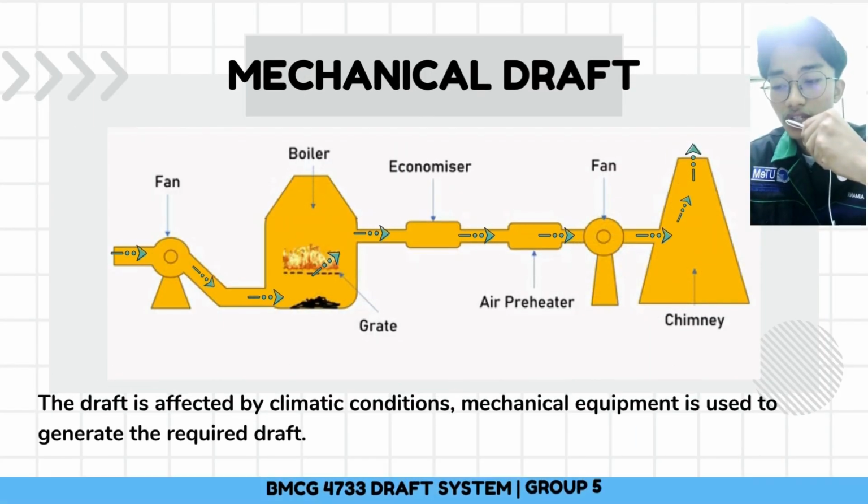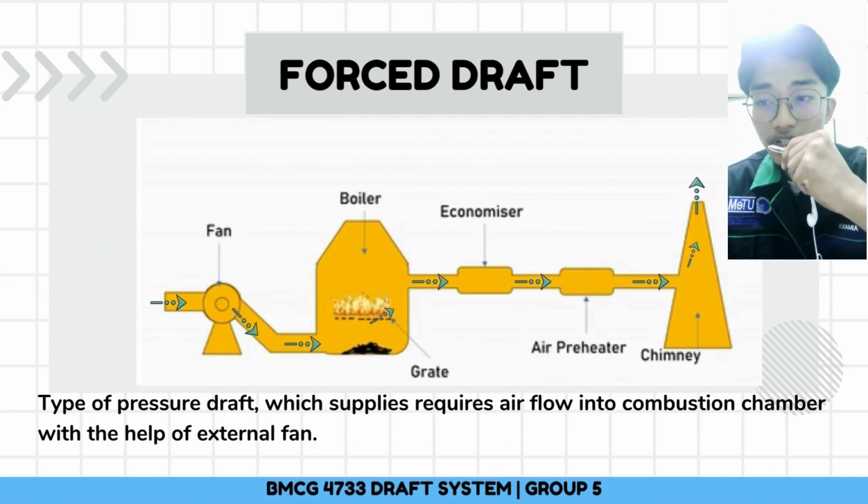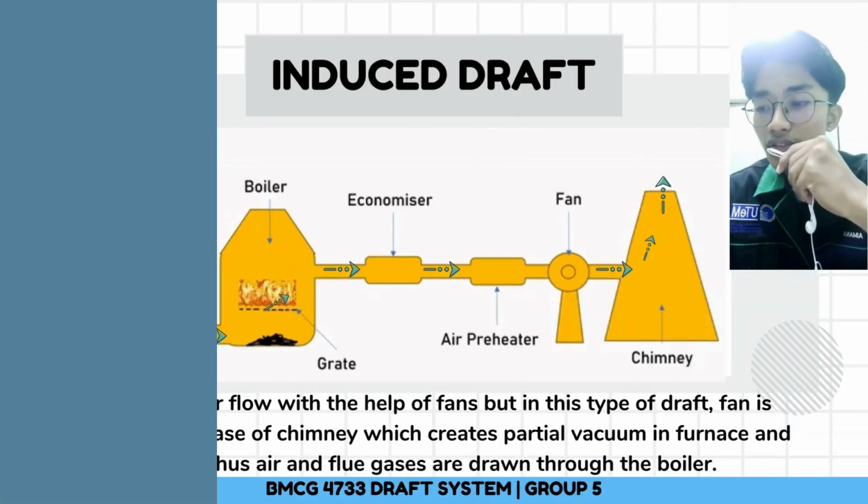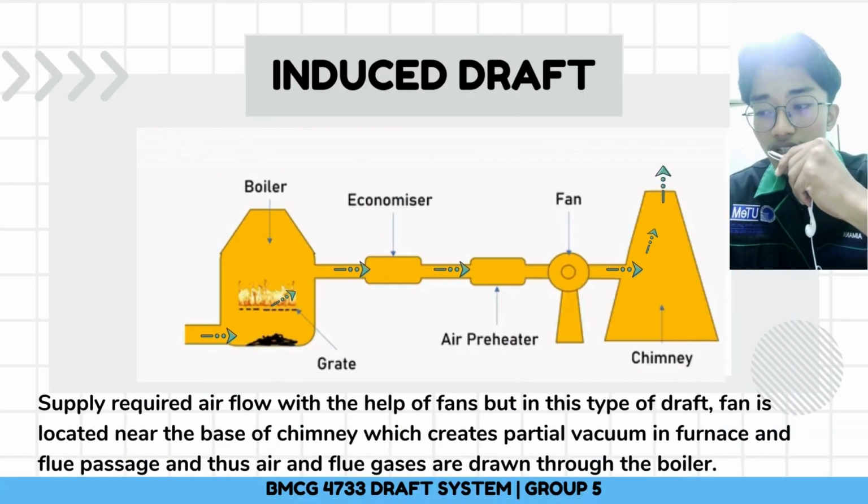Mechanical draft is developed to maintain the required supply according to the load adjustment, and this type of draft is used irrespective of the atmospheric condition. Forced draft is a type of pressure draft which supplies the required airflow into the combustion chamber with the help of external fans. Induced draft is used to supply the required airflow with the help of a fan, but this type